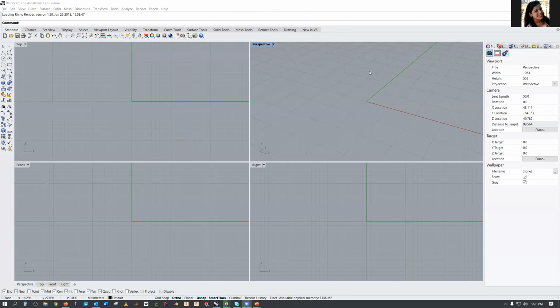So when you first open your Rhino, it'll actually have a dialog box and it'll ask what kind of template of file you want to open. I generally go with the millimeters and small objects because you can always make this bigger. And for me, 3D printing is all small stuff, so I always just stick with millimeters.